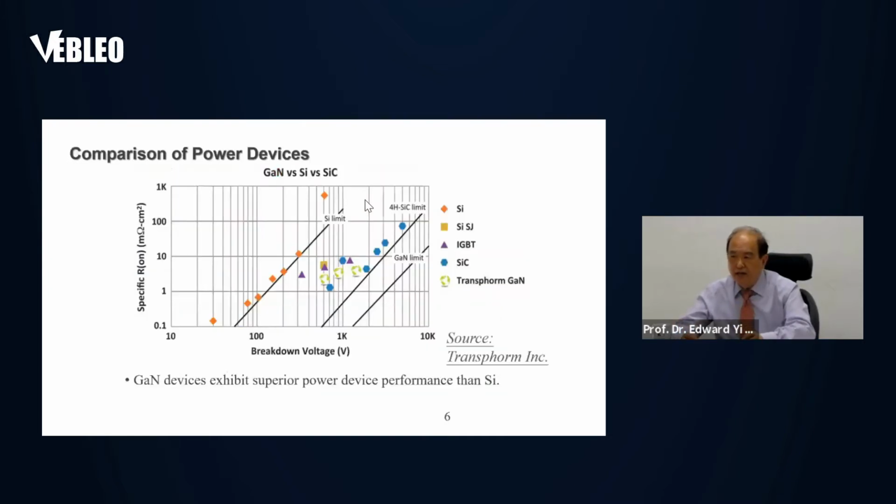And because of that, the material has a very high breakdown voltage and a large number of electrons, so the device is very good for power applications, because of the high current and high breakdown voltage caused by this material nature. So you can see the material has a very high breakdown voltage, and also the on-resistance is very low, because of the lot of electrons due to the 2DEG.